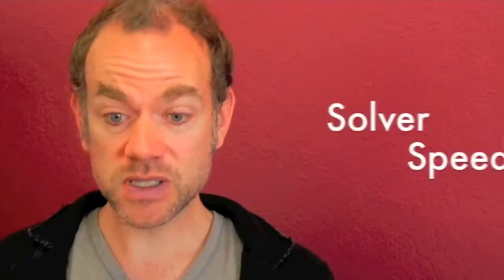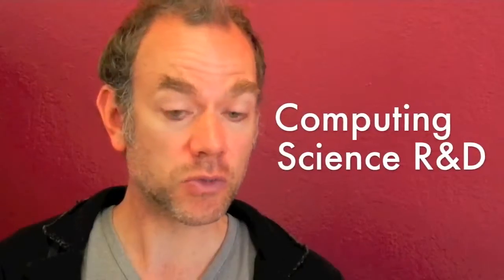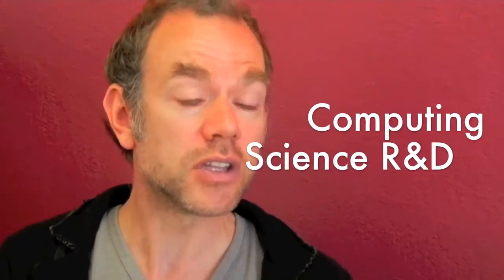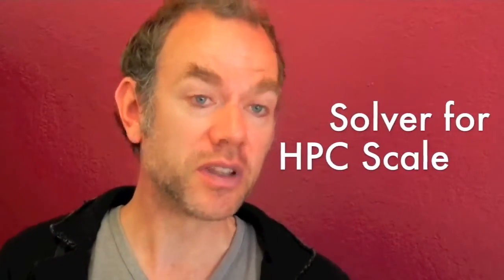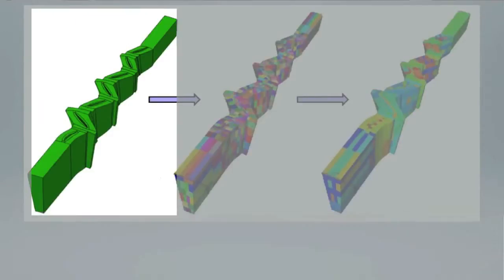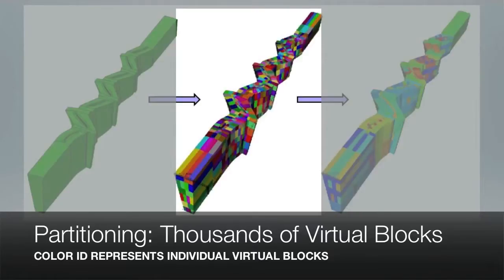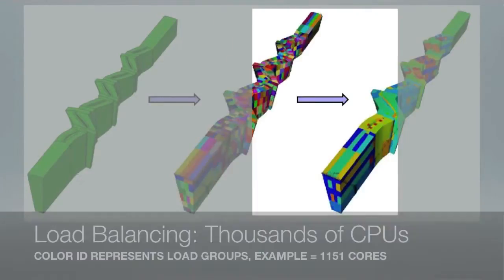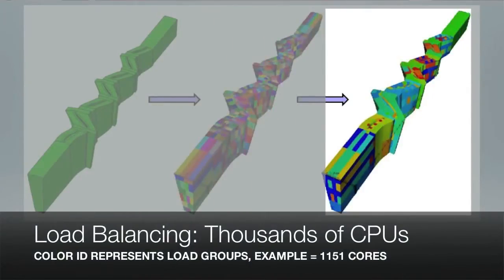All have tight schedules so the amount of analysis we can perform within a certain time frame is very important. The solver speed aspect is something on which we always insisted a lot in Fine Turbo, and the tool is now extremely competitive on that aspect. This includes fully transparent procedures to partition multi-block structured grids so that they may be easily distributed across thousands of cores while maintaining an optimal load balance.